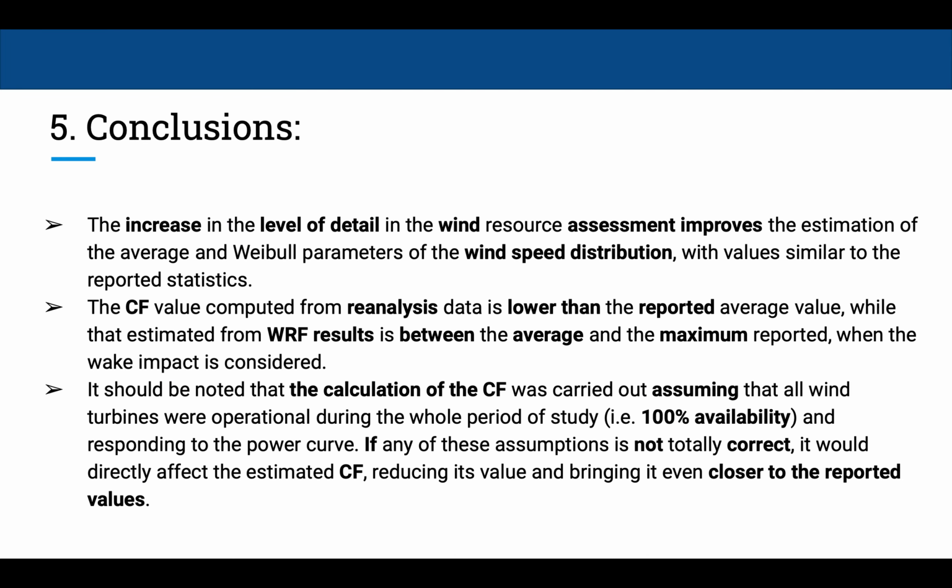Finally, I will say some conclusions. The increase in the level of detail in the wind resource assessment improves the estimation of the average and Weibull parameters of the wind speed distribution, with values similar to the reported statistics. The capacity factor value computed from reanalysis data is lower than the reported average value, while the one estimated with WRF results is between the average and the maximum when the wake impact is considered.